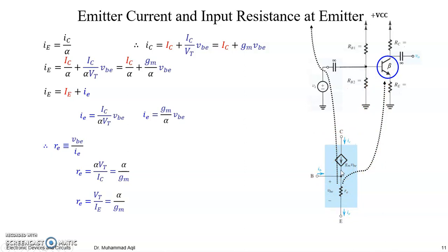For small signal active modeling, you would have a resistor at the emitter, right? Specifically at the emitter. It would be in between base and emitter, but explicitly at the emitter side, not at the base side. And this is a current source at the collector side, which would be our output terminal as far as the common emitter configuration is concerned.